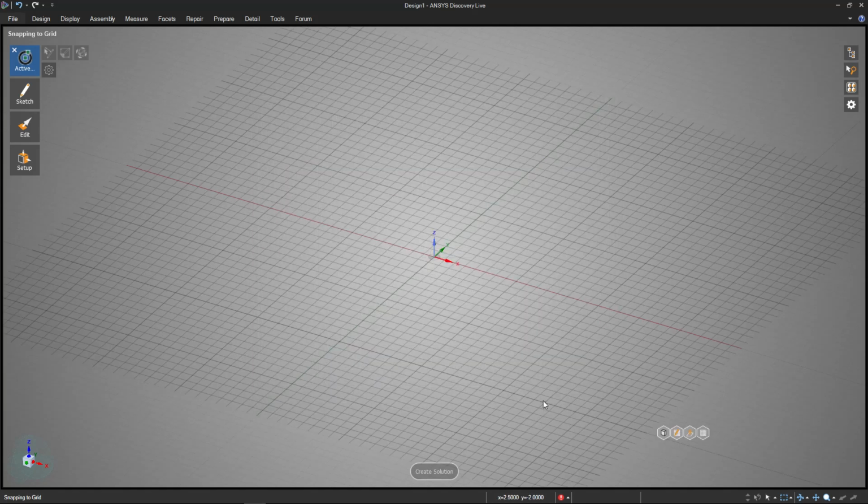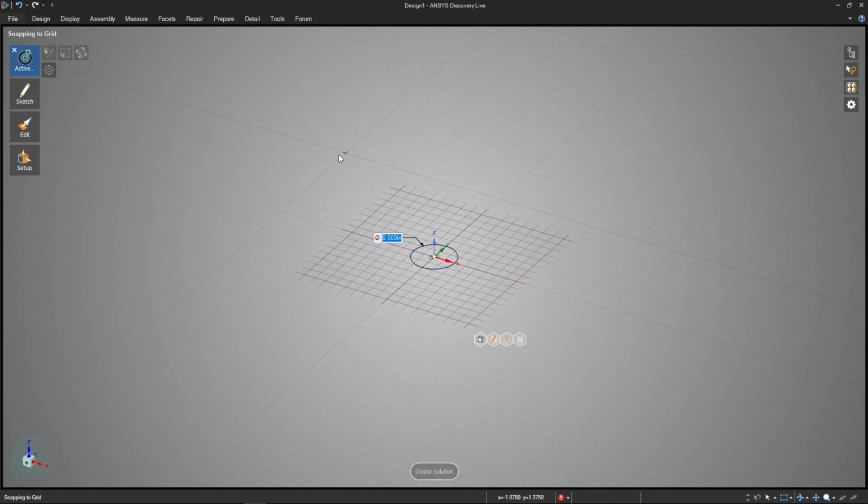So I'll say OK. Now when I go back to drawing my circle, the units there are the ones that are client defined. I'm going to type directly in with my keyboard 0.5. We have a 1/2 inch cylindrical rod that is the base of our cylinder.